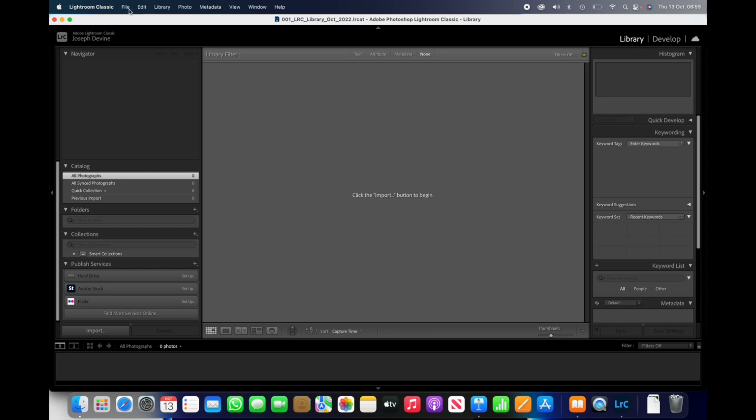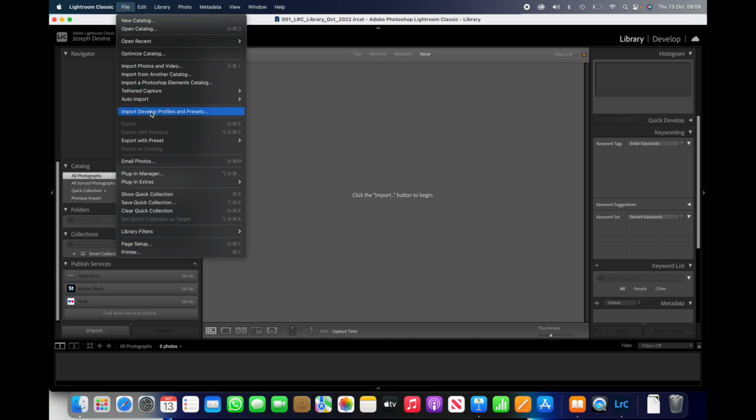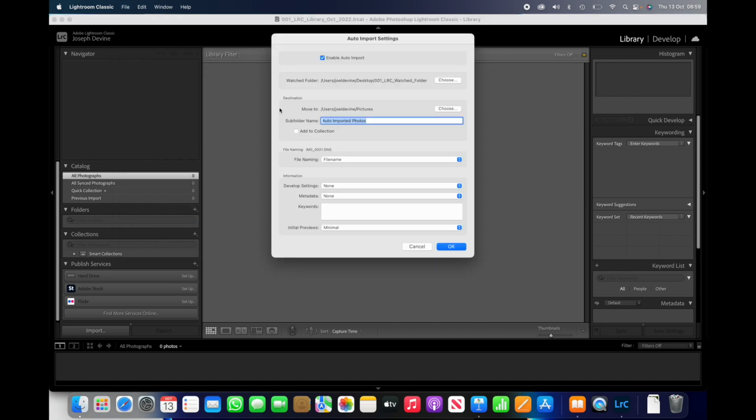From the menu on the top toolbar, select File by clicking on File, and then click on Auto Import and move over to Enable Auto Import and click. If you now go back through File, Auto Import, you'll find that Enable has got a little tick after it. Then select the Auto Import setting and click. You'll get up a window.